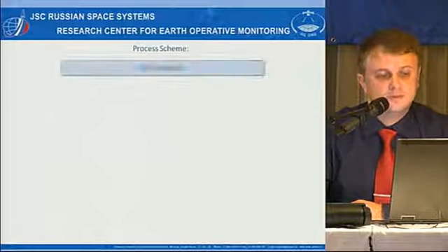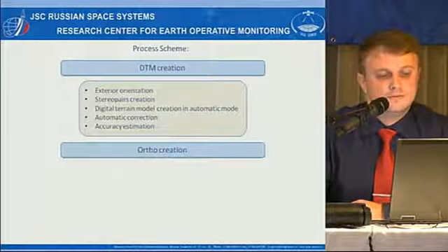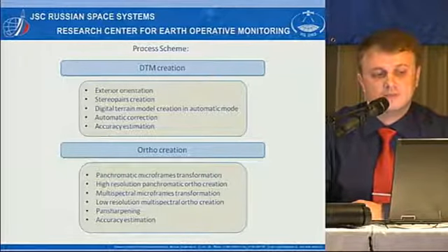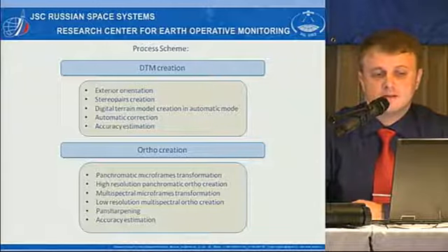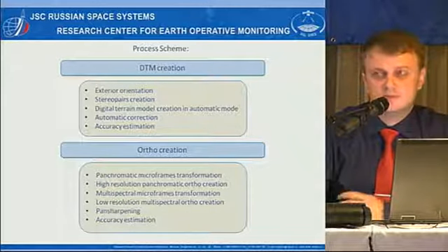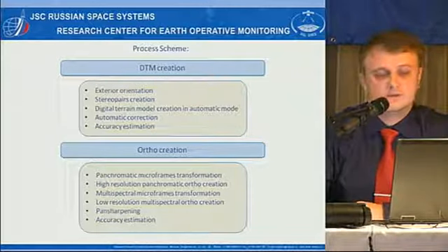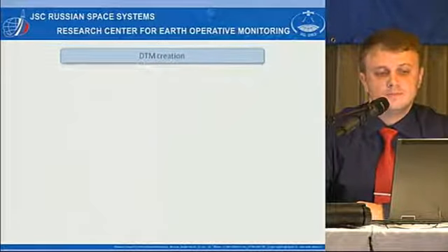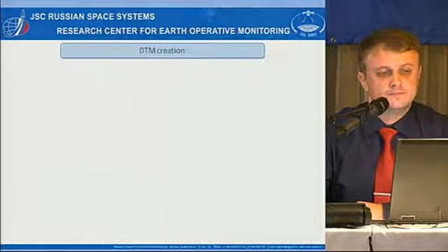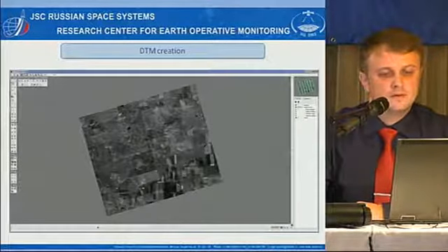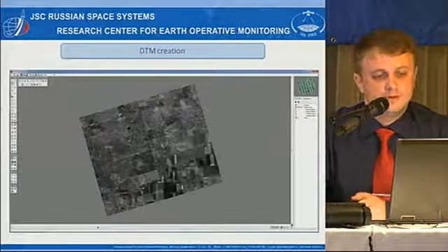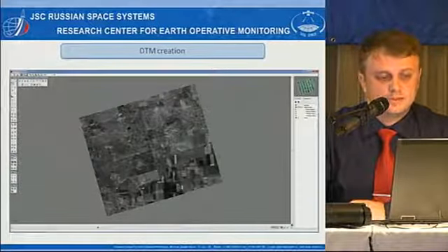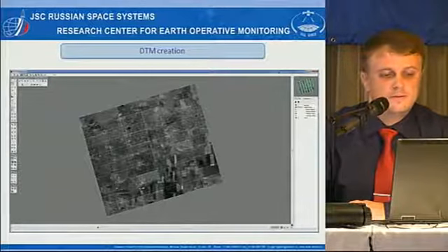This slide shows the process scheme. In fact, everything is quite standard. External orientation, building stereopairs, then digital elevation model, digital terrain model, and orthorectification. On this slide, you can see microframes from the panchromatic channel.